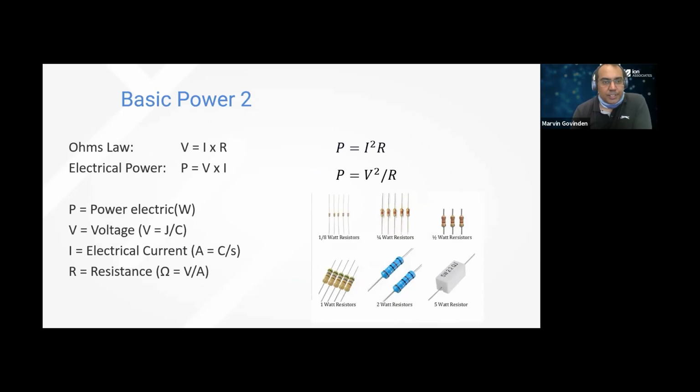On circuit boards, this is very basic. We select components. Sometimes we overlook those things, and we misdimension part of the circuit, and we get lots of local heating. I've come across this a lot, and sometimes we just slap on a resistor somewhere, and it seems to be working fine for a while, but it's actually working over its limit. It's overheating, it's burning. So yes, we have to check all the power ratings of our components on the circuits, and we can use these formulas to do that: I²R and V²/R.